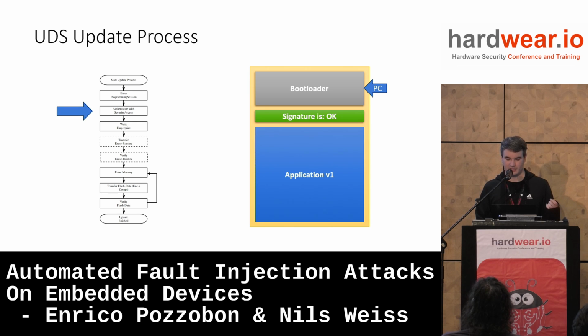Then there is a security access step, which is a cryptographic challenge response algorithm. This should not be considered a big wall or a big security feature, because this can be solved. The security access can be solved by any official repair shop tool, which are promptly leaked on car tuning communities all the time.